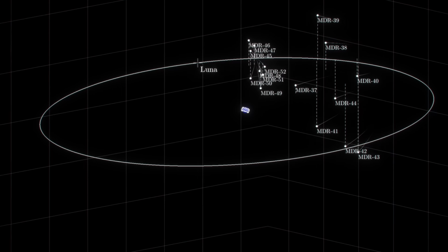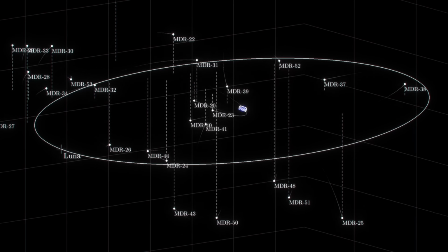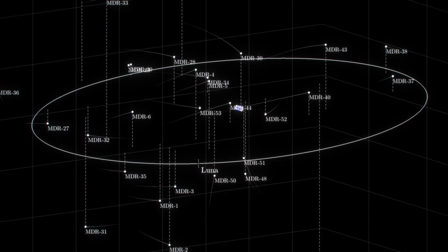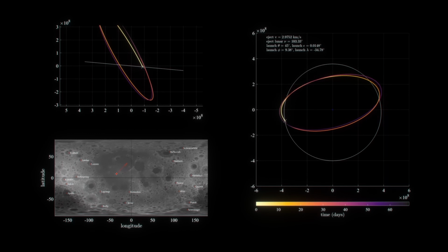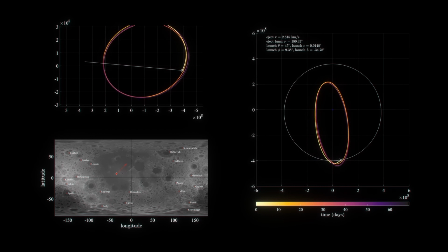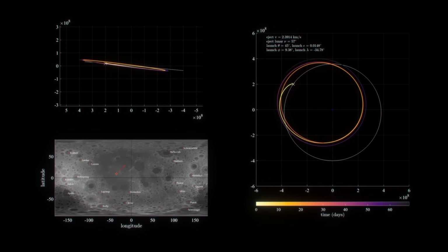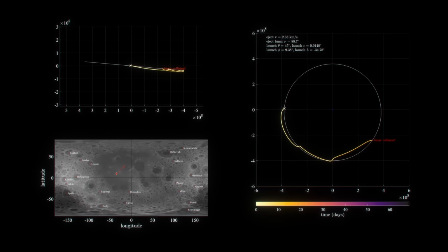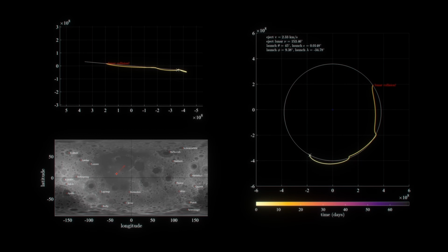This became phase 1 of the simulation work, what we called the allocation phase. The biggest variable we had to account for was timing. The moon is constantly moving around its orbit, so the lunar true anomaly, where the moon is when the launch begins, changes the geometry of the entire transfer. The target orbit is also precessing around Earth, so we also had to sample the target orbit's longitude of ascending node. Then we gave the optimizer the mass driver side variables it was allowed to play with: ejection velocity, lunar latitude and longitude, and the azimuth and elevation of the launch direction.